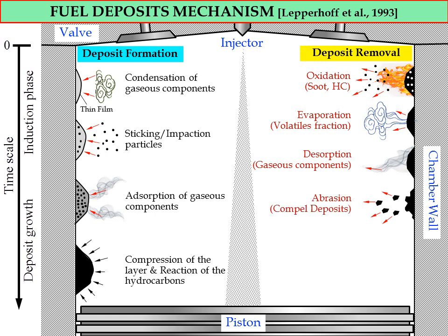And due to the abrasion process, maybe due to the movement of the piston and so on, the deposit will peel from the chamber wall. Okay, so due to the porosity of the deposit during the combustion process, the deposit will break off and detach from the chamber wall.